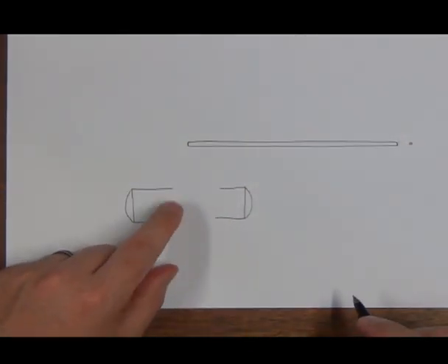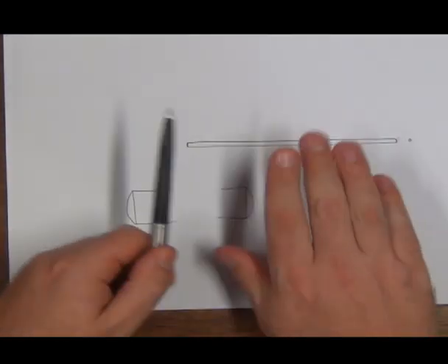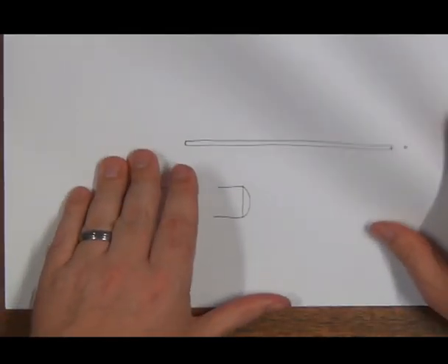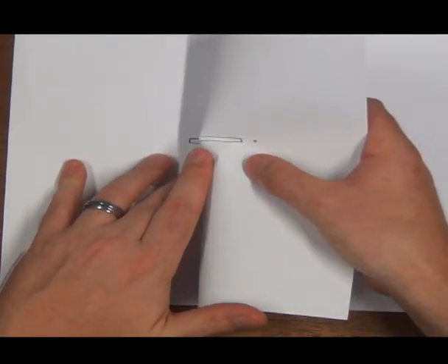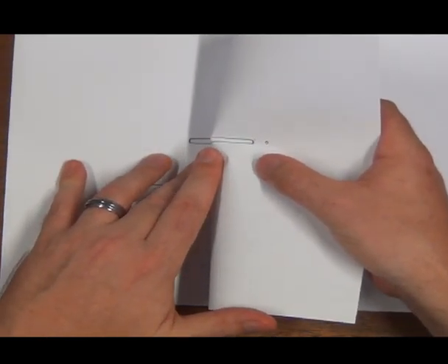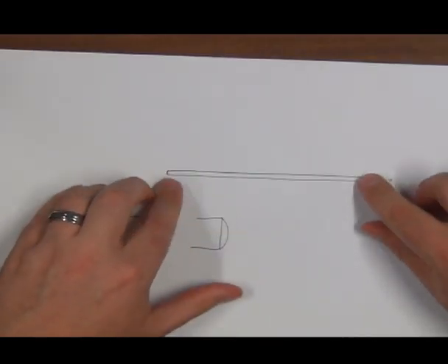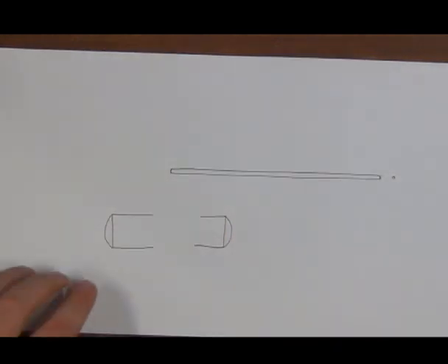So the standardized way to break a long object shorter, basically we're taking that part in the middle and we are just drawing it as if it was shorter. Although the dimension, when we place dimensions on this, we'll still use the original dimension. We just draw it in a shorter form.